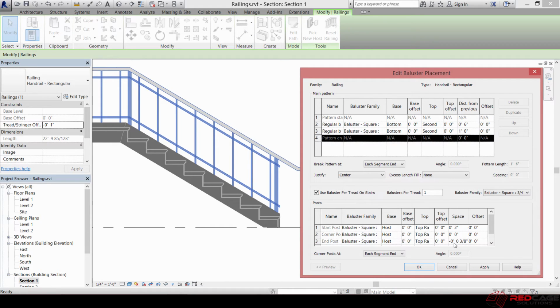If you wanted it to move outside, because maybe you have a decorative post or something that's not like a square or an equal profile, you can modify that. The offset is going to move it again, same thing as our railings or our balusters. This moves it horizontally, either away from the host or inside of the host, like into the stair path. So typically that's going to stay at 0, but the spacing you might want to inset that. So let's just take a look what happens if we put the corner post at 4. Okay, so we hit apply. That should move over.